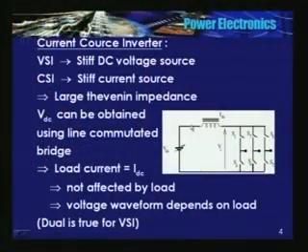This sort of operation we had seen in three-phase AC to DC conversion. Almost the same thing. At any given time, one device in the upper and one in the lower is conducting. Because it is the same principle, there also we had a load equivalent to a current source type.